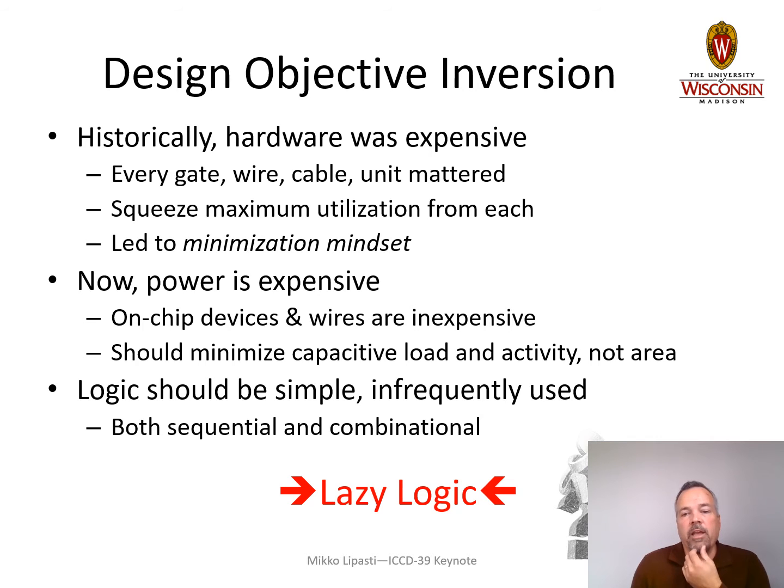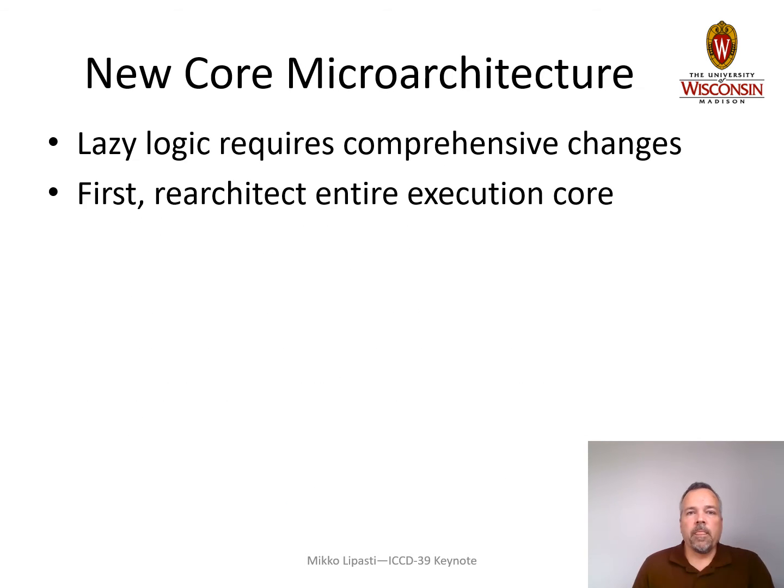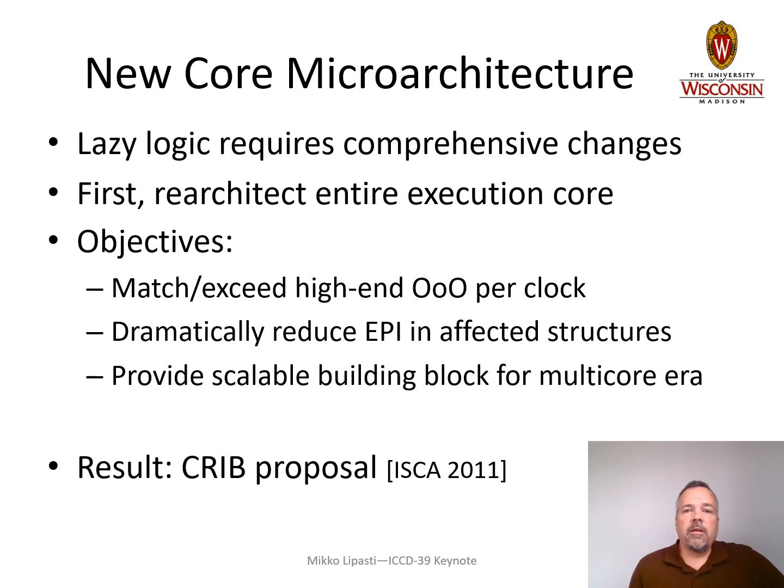And so we've been advocating for something that, for buzzword purposes, we call lazy logic, as an approach for designing future systems. To demonstrate the value of this approach to designing CPUs, we really needed to revamp the whole core microarchitecture. We had to make comprehensive changes to how things were done. And then we wanted to show that if we do this, we can build a competitive design, one with performance matching a high-end out-of-order core in terms of IPC or ILP, or per-clock performance, but with dramatically reduced energy per instruction in all of the affected structures.